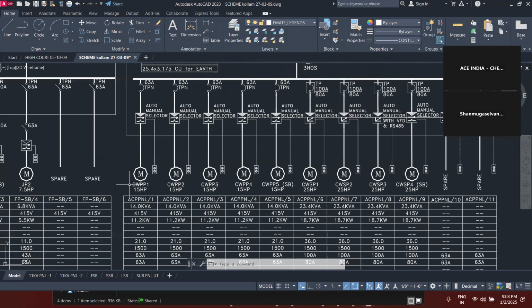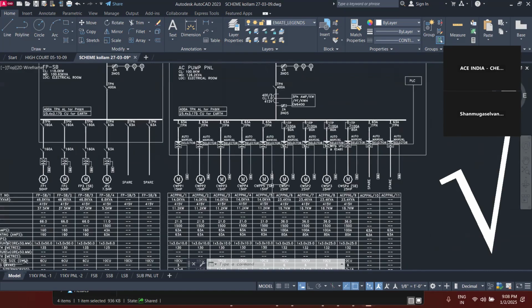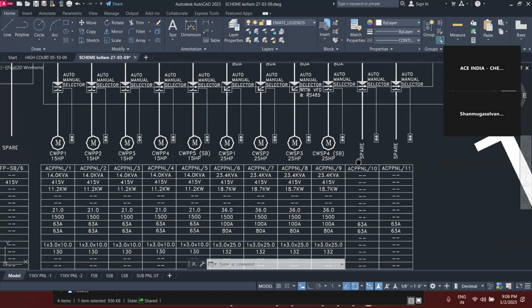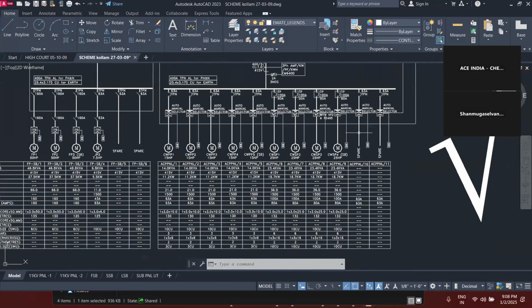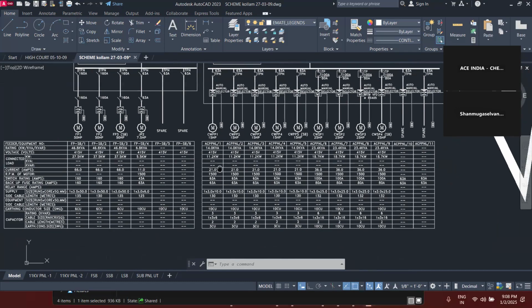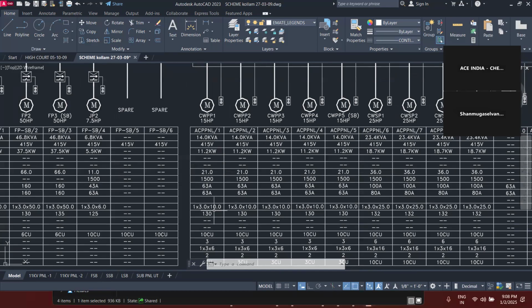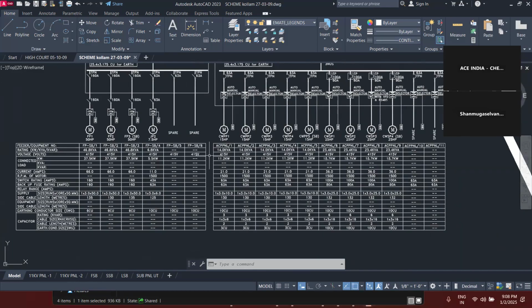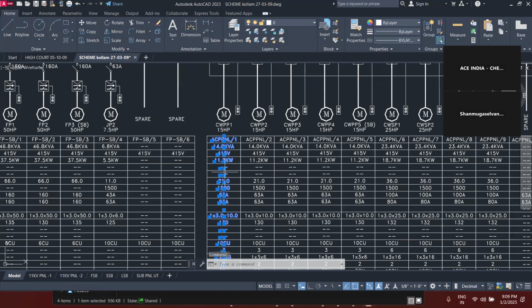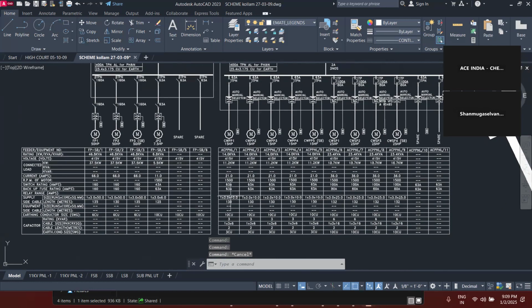Okay, so actually only single pumps are taken. There is no working or standby condition taken here. So all are working pumps. Then in future, if you are adding more, two spare conditions are also considered here. Okay. And similarly, all the calculations will be the same as we discussed earlier. The kilowatt, then the current rating, then the safety factor, then the MCCB rating, MCB rating, cable size, everything will be the same. Okay.